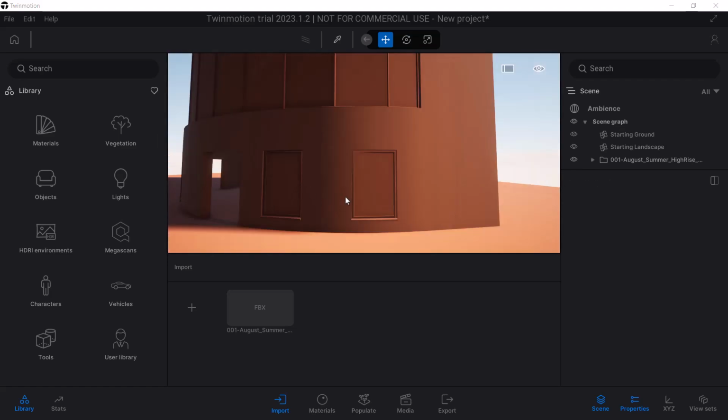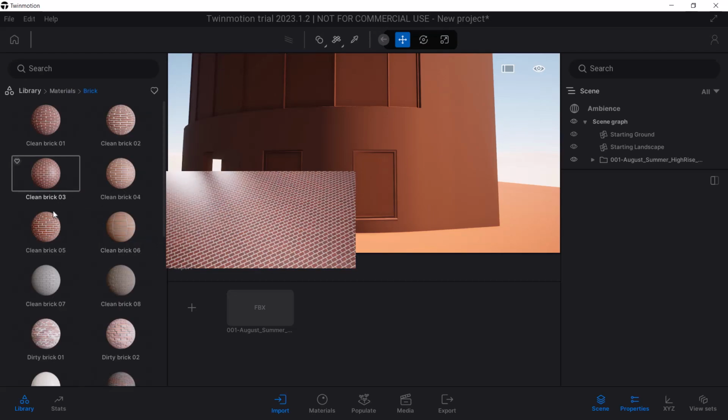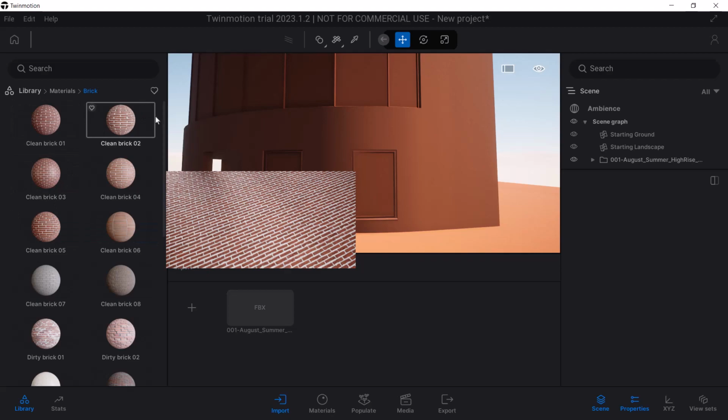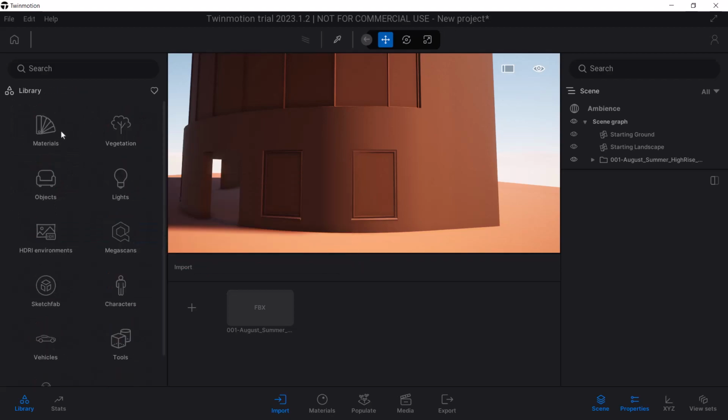To do this, I'm first going to drag the material for the walls. I want the wall to be some sort of brick wall on the ground floor here. I'm going to pick something like brick because I think that's what I used in Revit as well. So in Twinmotion, you have different styles of brick. I'm going to go all the way back to the library.